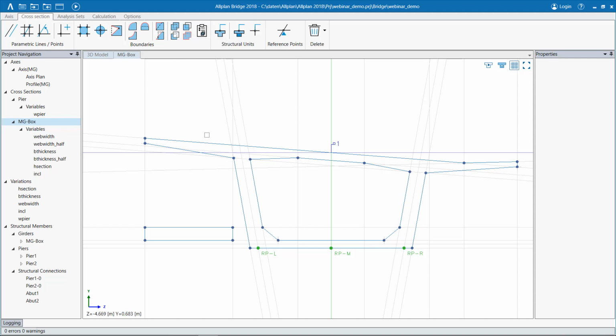So in that way, I can tell the program that the area described by the inner boundary, which should be a hole, should be subtracted from the outer boundary. So let's see, I can illustrate this here. Right, so here the combination has already been performed in order to accomplish this hollow.